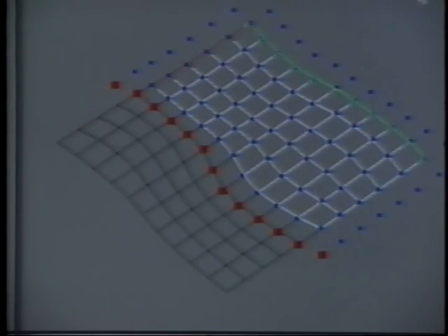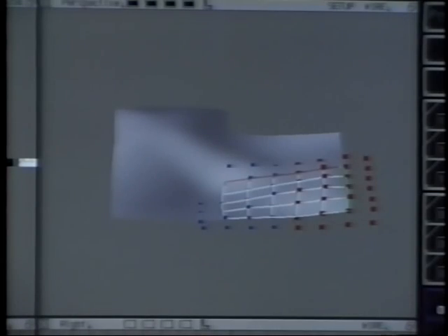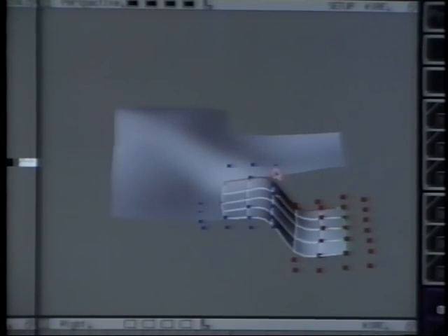We could delete points from one side of them while still preserving the continuity over the rest of the surface. We could also cut one surface and drag points to split it apart. All of this will still hold together on a skeleton as long as the control points that now match each other's positions keep the same weight in the global envelope.